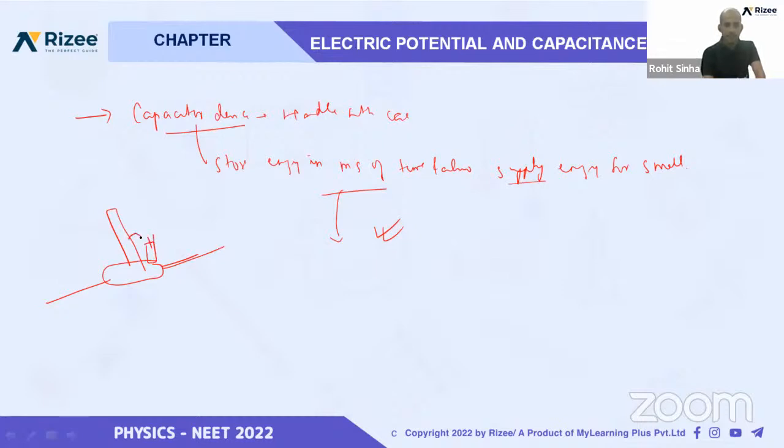This cylindrical capacitor takes energy from the electric current and gets charged, and instantaneously it also supplies to the coil, and with that energy the coil moves fast. If it does not supply to the coil, then the coil will move very slowly and the fan will only rotate slowly. So the capacitor provides extra energy and the fan rotates fast.